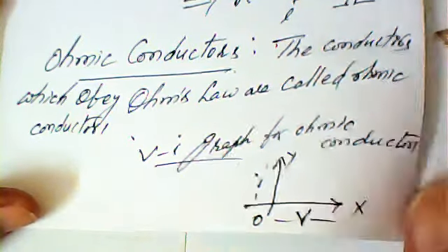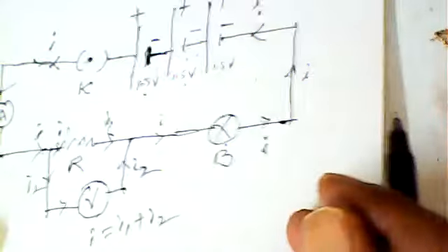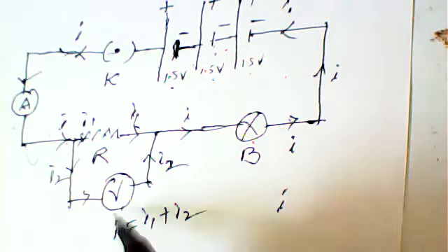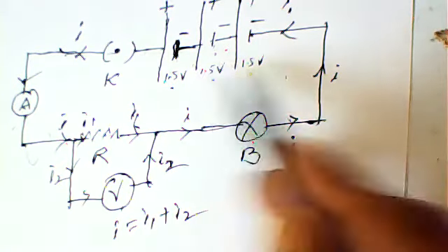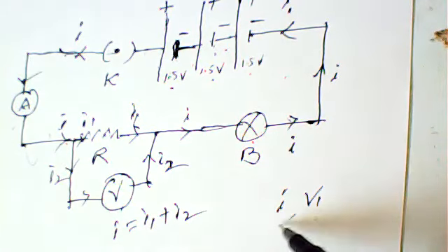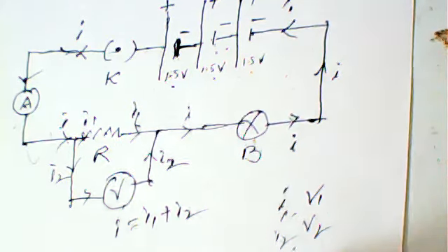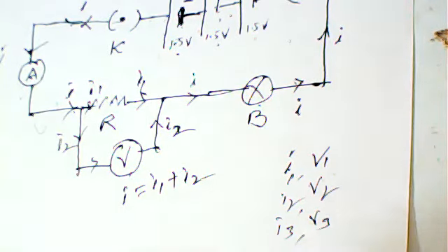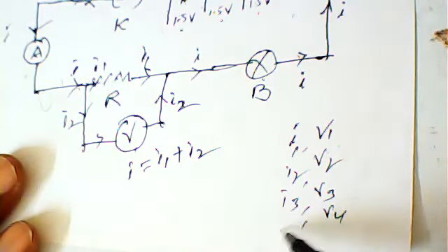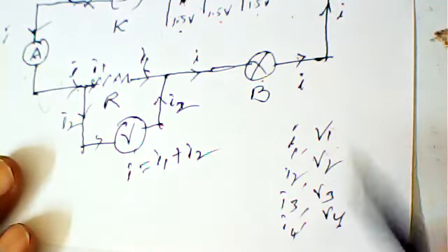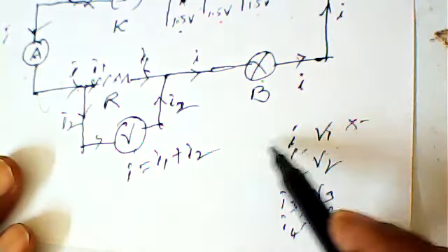Just now I have shown you a simple electric circuit like this. So just note down the current I, note down the voltage V. Now increase one more cell. Say this is V1, the first one, V1. Increase one more cell, the total voltage is V2. Note down the corresponding I2. Again increase one more cell, corresponding I3. Again increase one more cell, again corresponding I4. Now take all these values and plot the graph. Take the V values on the x-axis, I values on the y-axis. When you plot the graph, we are getting the graph like this.